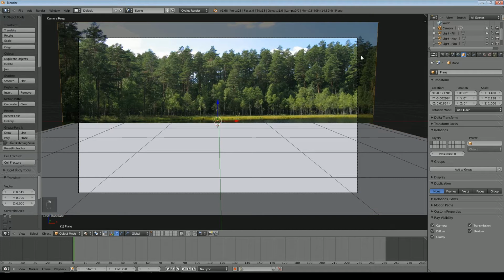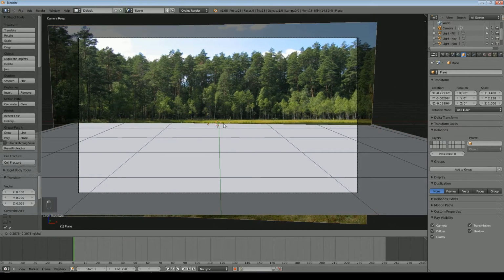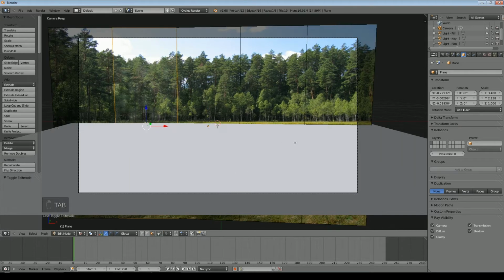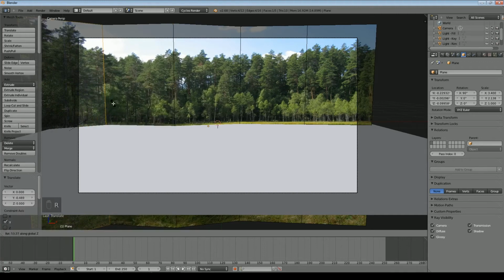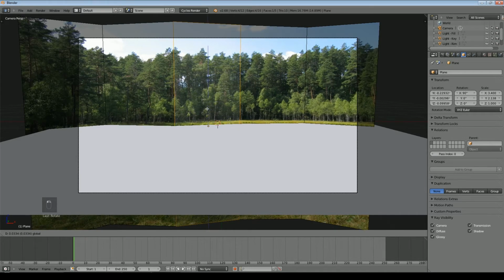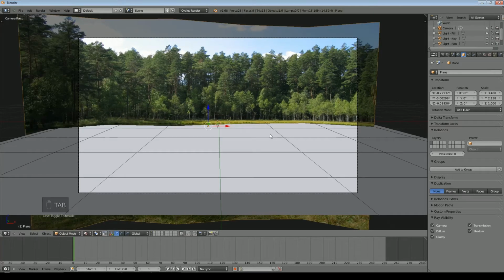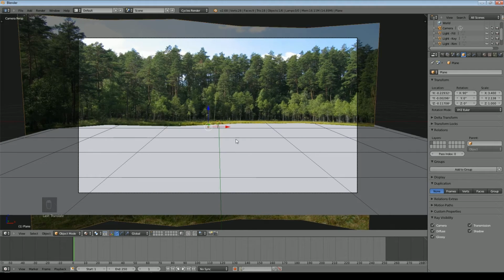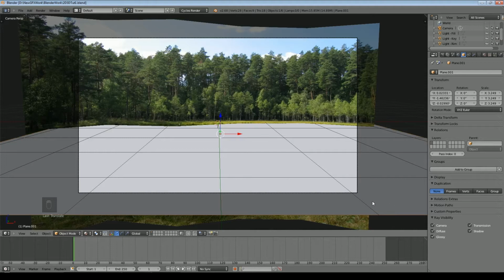So what I need to do is to distort this plane. The easiest thing to do is just set this so that we've got a little bit of bank there, but the rest is as it is. We can move it around a little bit in order to give it slightly more of a 3D effect. Rotate Z, and obviously we can even move things up and down like this. So roughly speaking, we've got our bank just showing above our flat plane here. So we'll save that, and we're ready now to create some water.